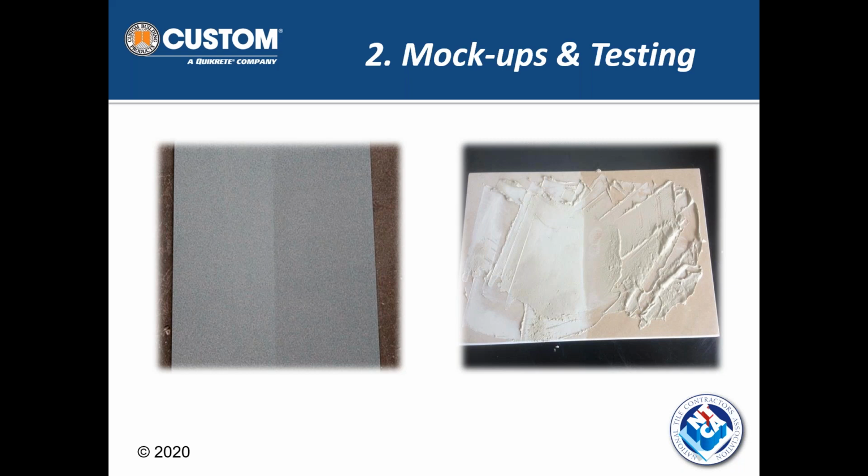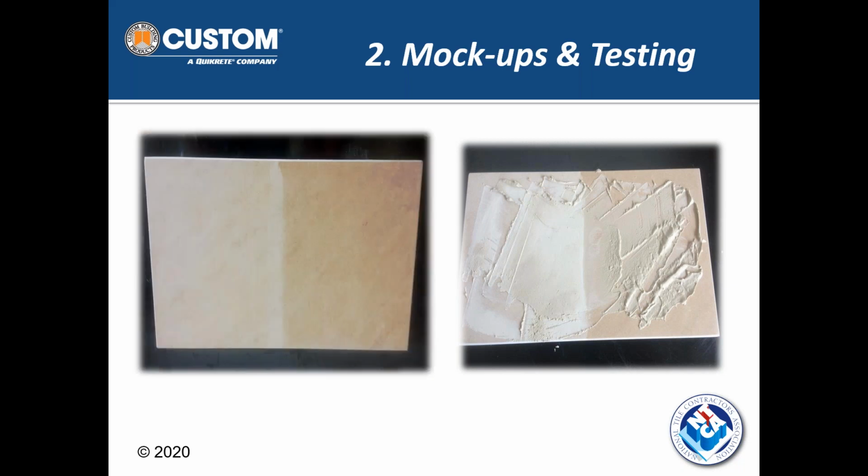This is a low density limestone. So going back to that, we're probably up in the 8, 9, 10% absorption rate at least with this stone. It's just pulling the moisture out. So it's stiff. It would be hard to grout that stone without pre-sealing it. So again, something to look at.